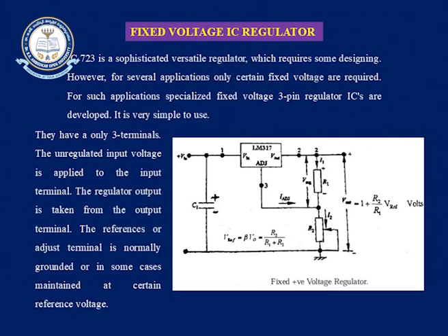So, here you can observe that this is the input voltage, this is the output voltage we are considering, and this is the IC here. Okay. LM 317, this is the input voltage and this is the output voltage. So, here ADJ is also there, and here the fraction of the output which is fed back into the input is also to be considered.